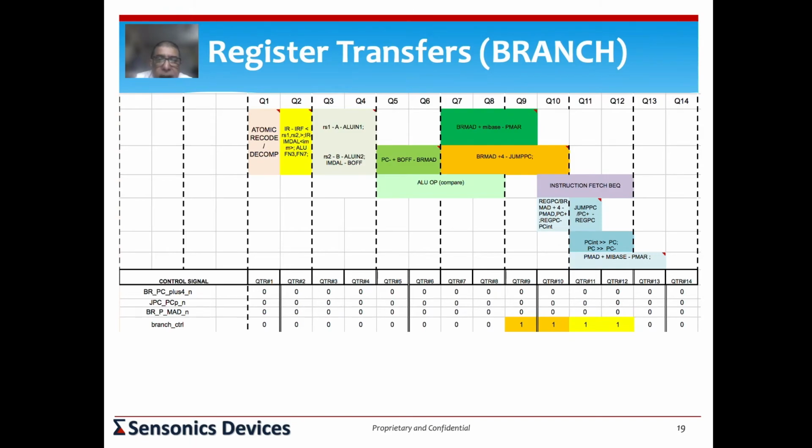And if you didn't have it, somebody is using another register and you didn't collect that, then you go through the whole cycle. Or you're building a really, really low-end machine and you don't want to do all this caching, then also you go for the full cycle whenever there is a jump or a branch.